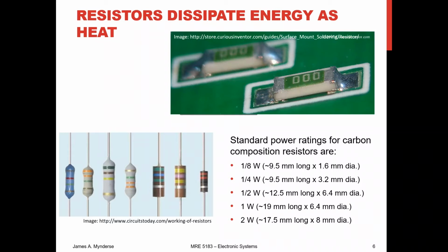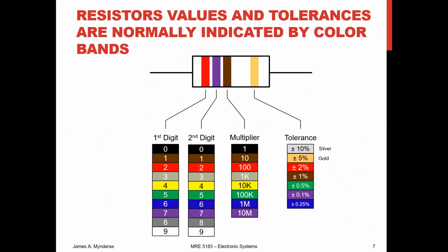the right components. When you are choosing your resistor, certainly you're going to go by your resistance value. You should see a color-coded band on the resistors that tells you what the resistance is, or at least the nominal resistance. So a lot of the stuff that we've got is going to be 3 bands worth of value and then 1 band worth of tolerance. You've seen these before. You're going to read the bands and identify the numbers, and then put those together as first digit, second digit, multiplied by the multiplier, and then plus or minus some tolerance.